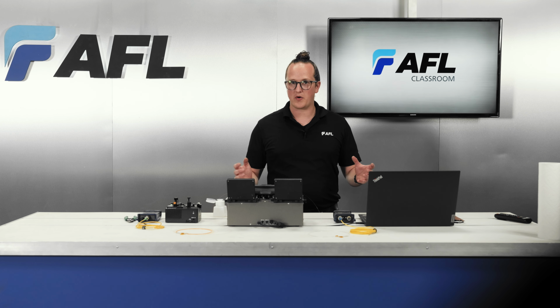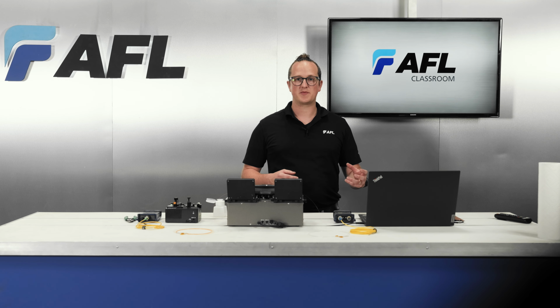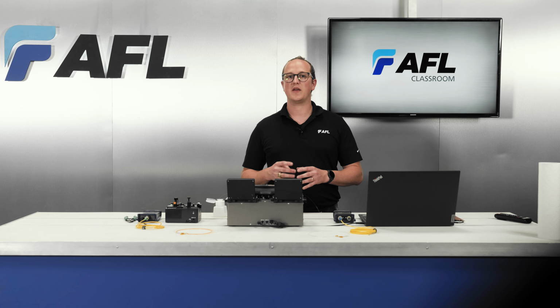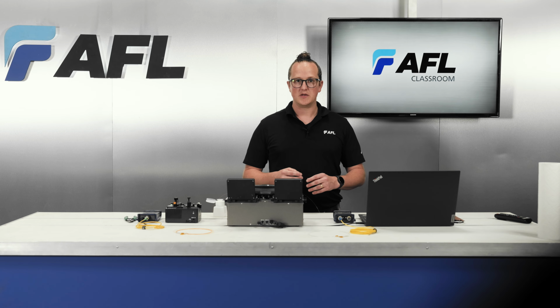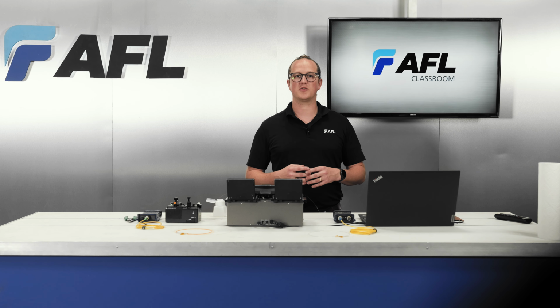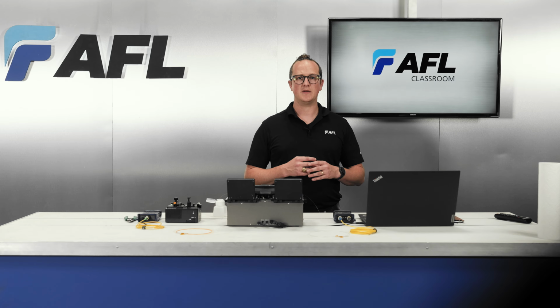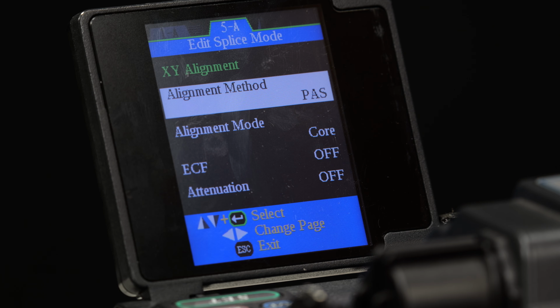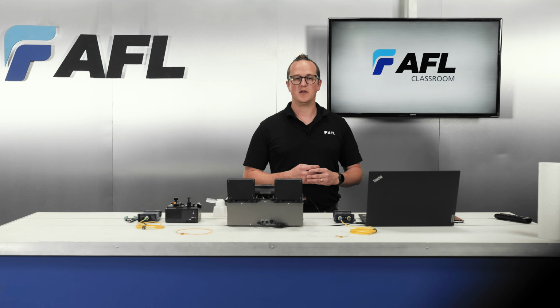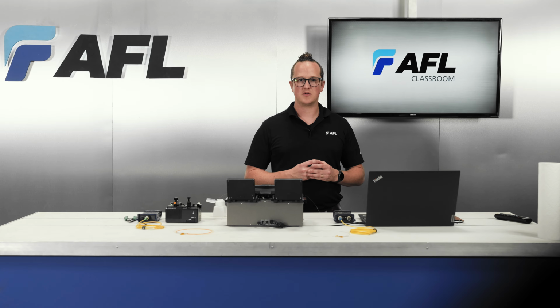After identifying your starting point, we can get started optimizing the splice parameters. I'll revisit the information laid out in the previous video and start with entering my basic fiber information, then move through the splicer setup and fiber preparation. For the sake of time, I've already done this, but you can refer to the previous video for a more in-depth, detailed explanation. After that, I'll choose my alignment methods based on the fibers I have and begin adjusting the splice mode parameters.